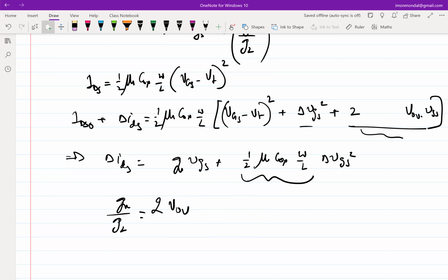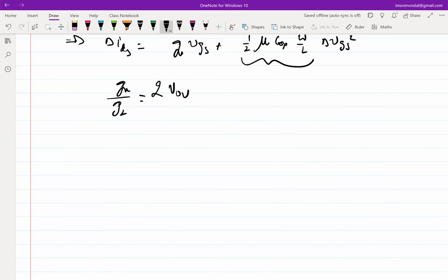Okay, so clearly, as a designer, this directly tells you that if you have to increase linearity, at least if I limit myself to second order distortion from the simplistic model that I have, it seems like increasing the quiescent overdrive is the way to go. And that should make sense. Why? Because ultimately, what is the root cause of distortion in the current?